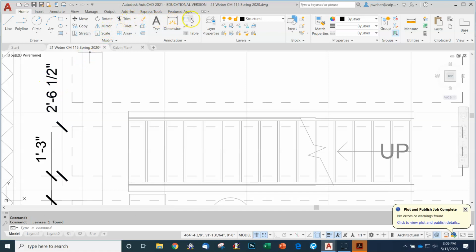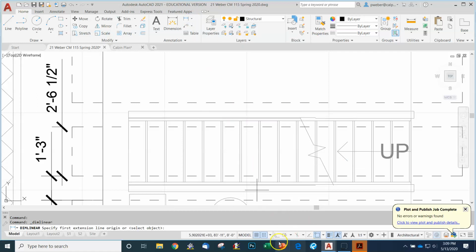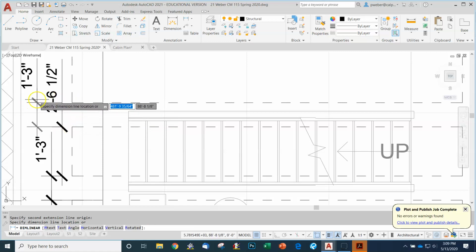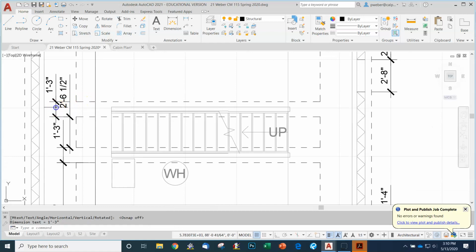When I say it's a bit tricky, you just have to know when to put the clutch in when you shift gears. So I'll click here. I don't want snap on. O-snap I want on. I'll click from here to here. It will tell me it's a 15-inch foundation. Let me turn off O-snap, which is F3, because it had a tendency to snap back down here. And let me just float this thing up a little bit high.